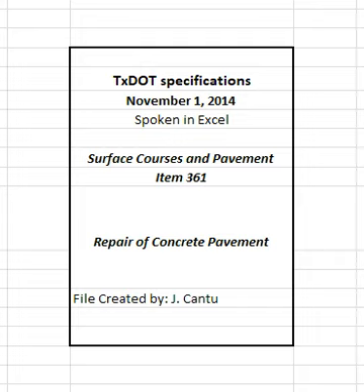Mix, place, cure, and test concrete to the requirements of item 360, concrete pavement, and item 421, hydraulic cement concrete. Broom finish the concrete surface unless otherwise shown on the plans. Perform a timely saw cut over the dowel bars and restore the transverse contraction joint for CPCD. Restore the existing longitudinal joints to the requirements of section 360.4.4, joints.